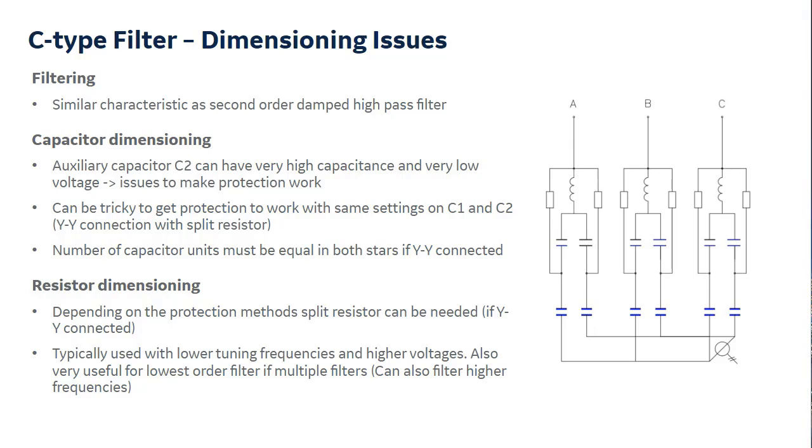And the double tuned, in some cases, is increasing the demand, but this is what I have seen and what I have designed. This is perhaps the most typical filter with these wind farms. So this is very, very typical there.